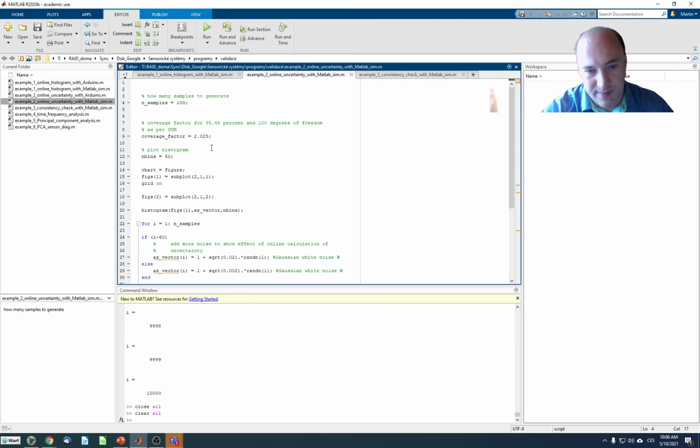I need to specify what is a so-called coverage factor, and this is based on the document that's called Guide to Uncertainty of Measurements. In short, it's called GUM, and it is also based on the expected probability distribution of my system. So I am assuming that I have a normal distribution and that I want to have confidence in my calculation to be around 95%. For this case, you find in this guide to uncertainty of measurement that something that's called a coverage factor should have this value.